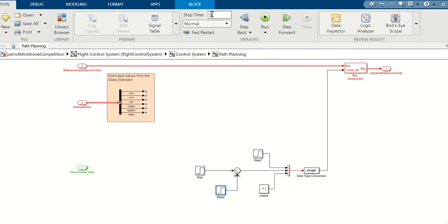Now, if you go beyond about 22 seconds, the drone can only store data for about 22 seconds. The memory on board the drone only has about 22 seconds of capacity because it's storing every 0.005 of a second, which is 5 milliseconds. So it's storing about 200 points of data per second, and it only has capacity for 22 seconds.